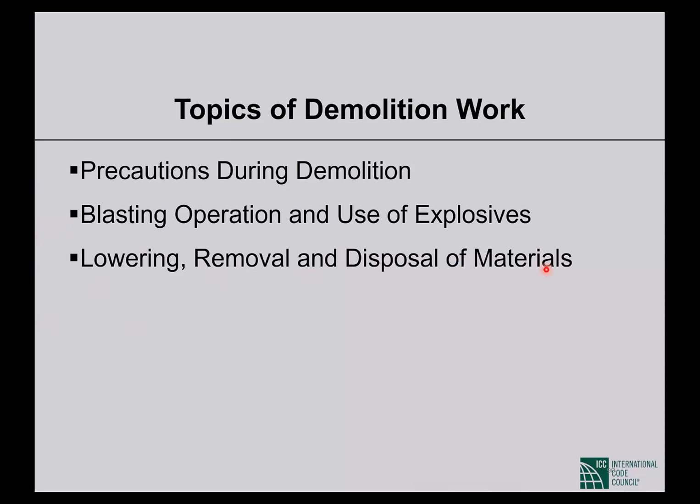Lowering and removal of disposal materials. This is very important. This is the reason why Ranks building collapsed. The debris after breaking walls and columns and shear walls was kept on the slab. And then they were breaking those shear walls. The shear walls were cut from the bottom and put on the slab, and they were hammering the shear walls and breaking them. And there was a lot of debris on the slab. So the amount of load was much higher than the design load.